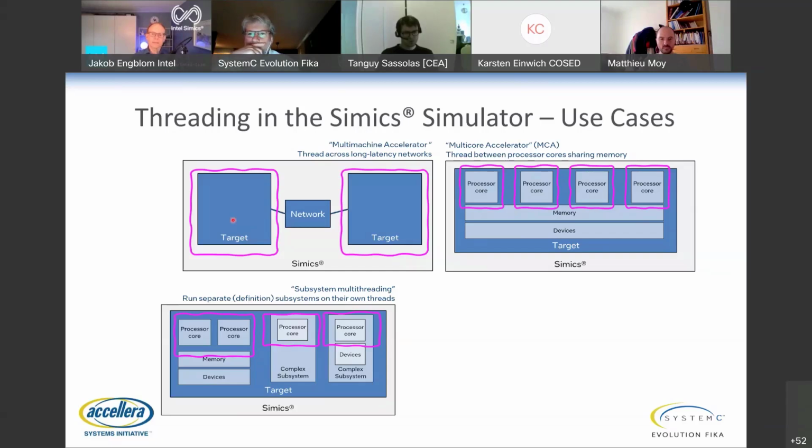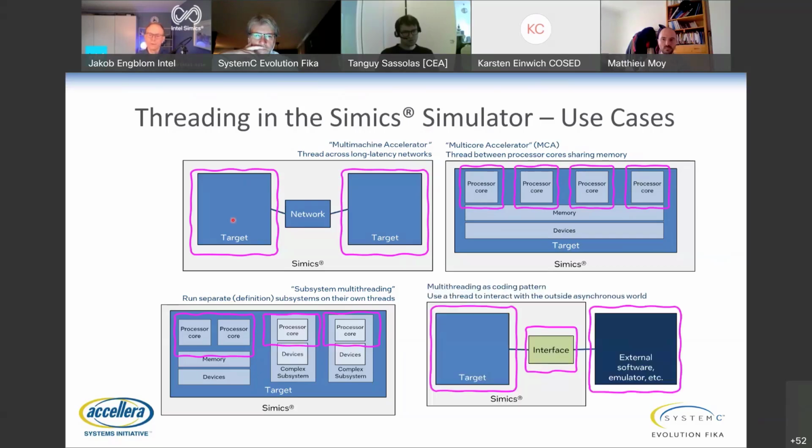And these guys, we want to kind of parallelize out all the execution in these embedded firmwares because they can take as much time as the big IA cores to run because they are active all the time. So one very important use case is really to kick off these subsystems on their own threads, and maybe it's okay to have round robin between the big IA cores because they're not actually doing all that much anyway. I mean, most of the time, most software nodes do nothing. You have to work hard to get more than a few threads running. I mean, typically you need to be actually running a threaded workload.